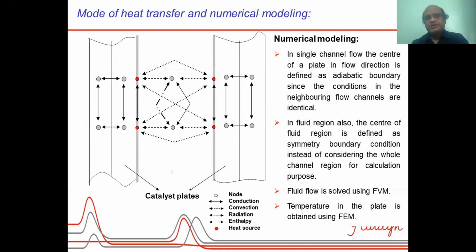In the model that we built, we used the finite volume method for the fluid flow, and the chemical reaction was modeled using a surface reaction module at the surface, which releases heat at the surface, and then heat conduction in the structure is modeled using the finite element method. This is a transient problem, and we need a time-accurate solution, because it is also important how much time it takes for the recombiner to remove the hydrogen. These three solvers were coupled in an appropriate manner.